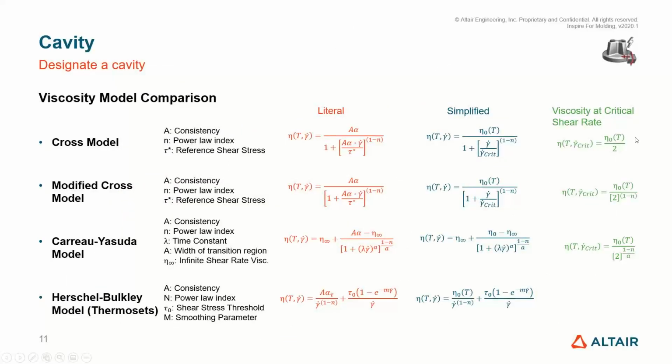All right, so viscosity models, right? So we talk about viscosity and pressure drop. Viscosity for these polymers is not linear. It's not Newtonian, right? When I change my shear rate, my viscosity changes. So as I'm increasing the speed of my flow incrementally, as I get faster, it takes less and less pressure to keep adding to the speed of the flow. It still takes more force to get that to happen, but the incremental amount more is not linear, right?